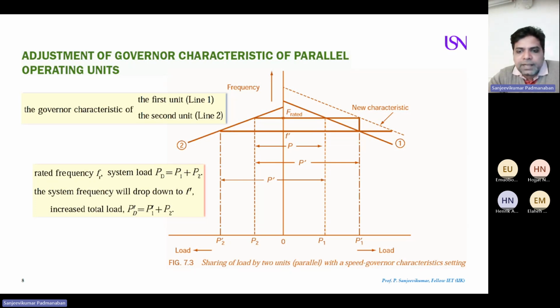Now I'm going to look at the characteristics at two different power points, say 0.25 per unit or 0.5 per unit. I can say this is 25% of your load or 50% of your load. Similarly, on line 2, 25% and 50%. I'm just picking up the line towards my speed plot characteristics. You can see at 25%, I just touch this margin. Of course, I put it here and extend the point P2.